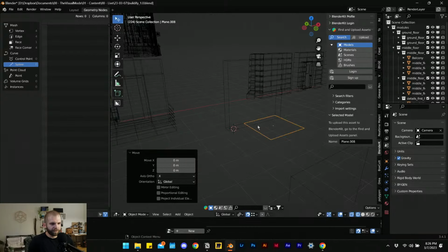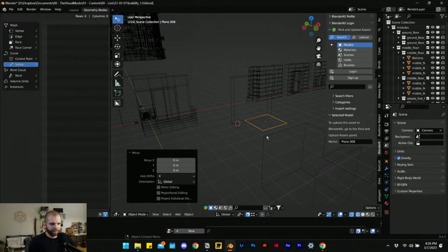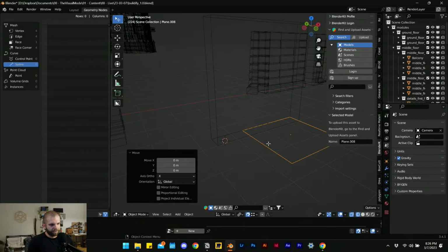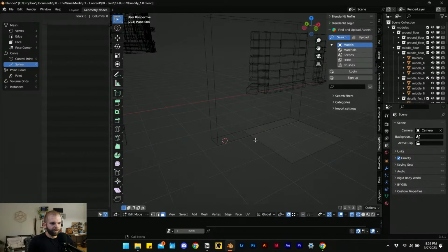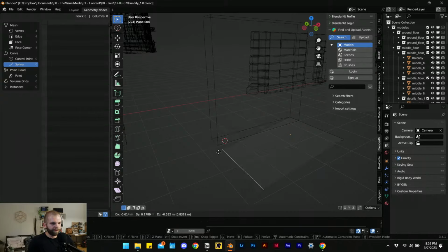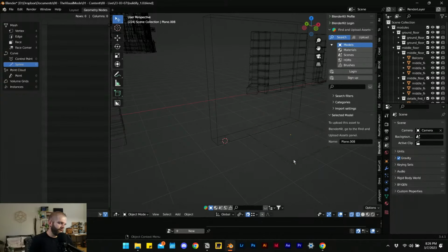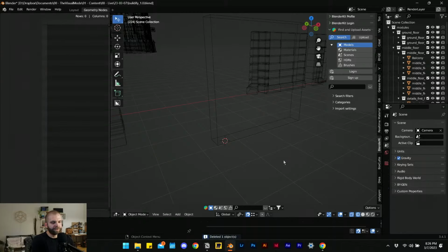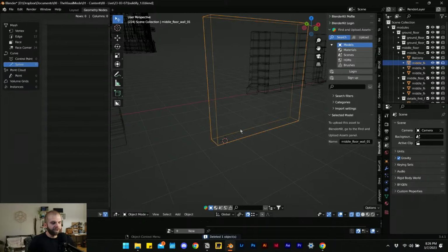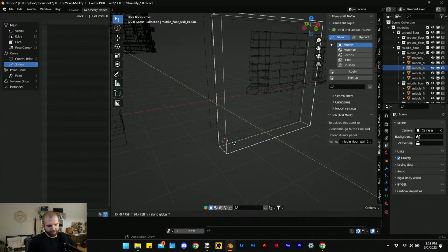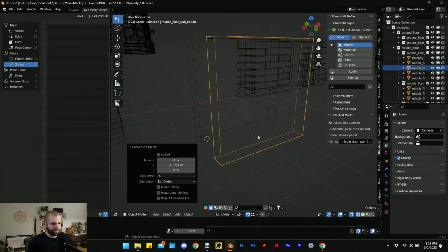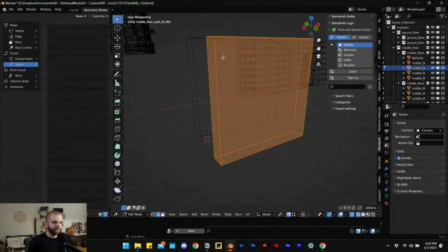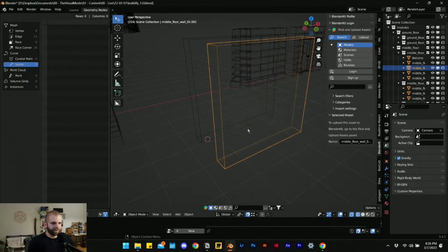So actually, this was a part that was a bit tricky. At this point, I could go into edit mode and start moving these edges so that it aligns. So I'll go over here and hit edge mode, and I start moving this to basically copy this profile. Honestly, with this main file, I generated a new plane just to see if it would work, but you could even just work off of this main one. So if I duplicate it and just move it forward, we have the origin where we need it. We can just start working off of this existing rectangle.